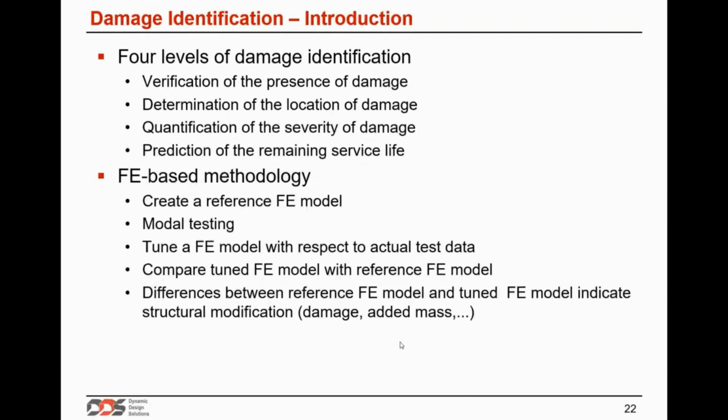So how many vibration cycles have been measured, because there is permanent instrumentation that can do that. Using rainflow counting, it's possible to count all the cycles, and then you can predict how far the structure has progressed in its service life, and if it's faster than planned, then it may need inspection and repair.